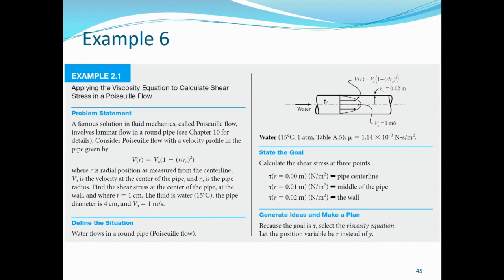We'll explain a special case of liquid flow or water flow in which there is local compression. The density reduces because of abrupt closure of a valve or so. That leads to what is called water hammer, which we will explain in a few slides to come. So here, consider the Poiseuille flow with the velocity profile in the pipe given. This is the formula for the velocity profile in radial coordinates in terms of the radius. You can see that. So this is V naught.